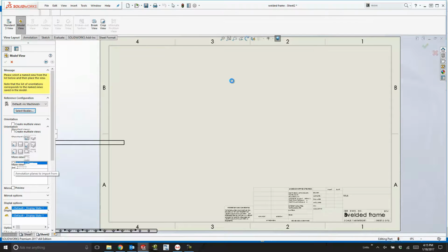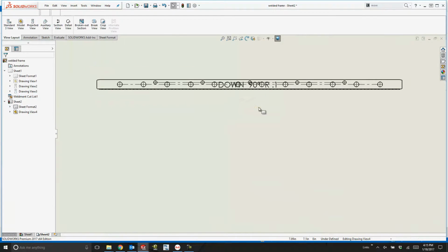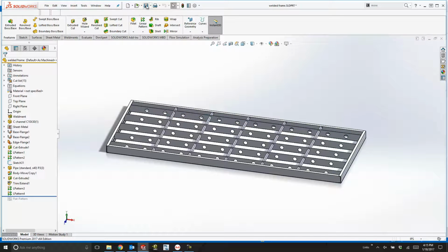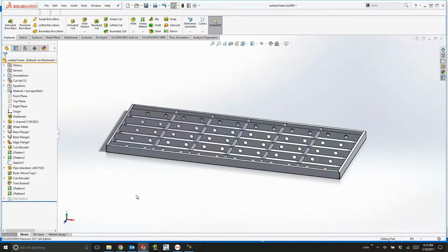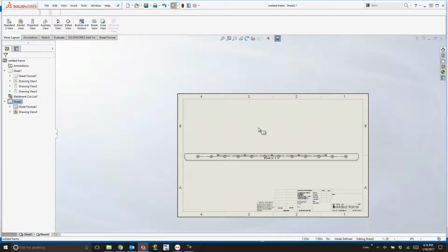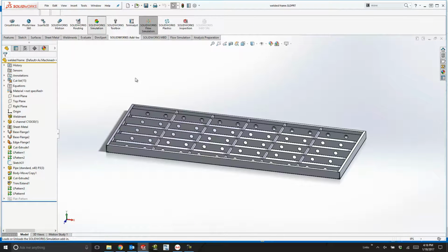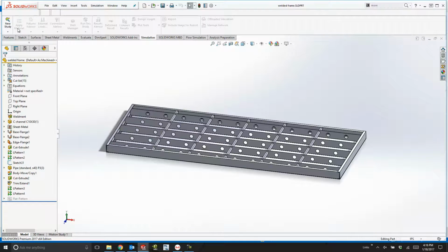So I got a couple ways I can do it. Quick right click at the assembly level or at the part level, and I can export to a 1-to-1 DXF or DWG. For this flat pattern, I also created a flat pattern on the drawing so you could see it. I had to roll back to finish that design up, but there you see there's the flat pattern, so I can detail it out so that even though it's a multi-body part, the whole thing is one big part, it's still very simple and easy to document each individual piece as needed.